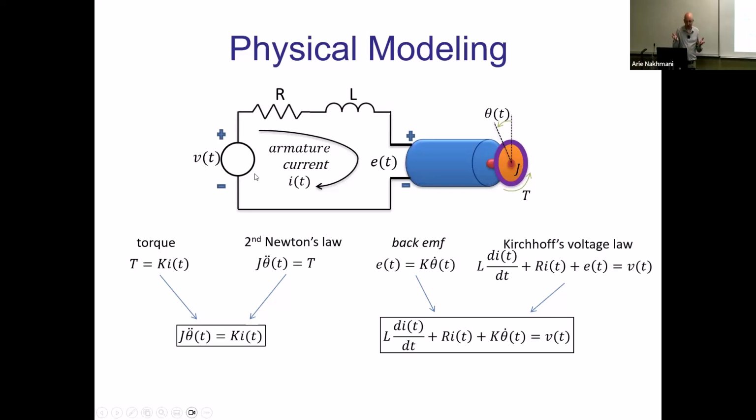Now, essentially, I want to bring these 2 differential equations into one differential equation of higher order, because I want something which connects V to theta, right? These are the equations that I want, which describe that entire system. So I want to blend these 2 equations somehow in such a way that I will have one equation of 3rd order, but this equation will not include I, because I do not have anything with I here, right? It's just the current which flows. So I know it exists, but I'm not measuring that directly or not providing it directly.